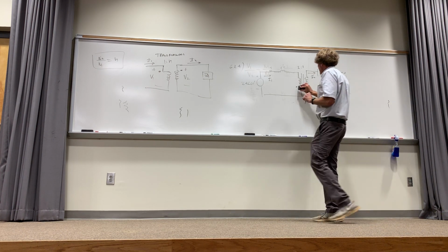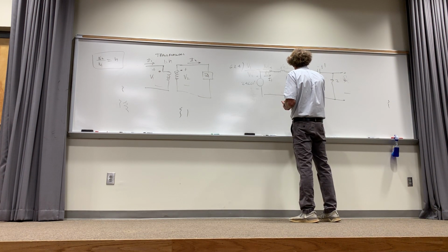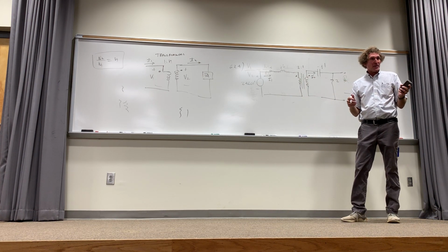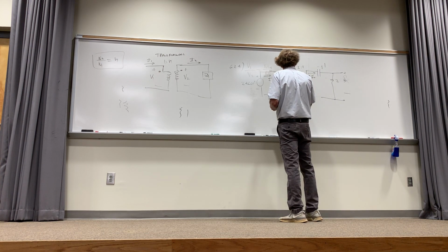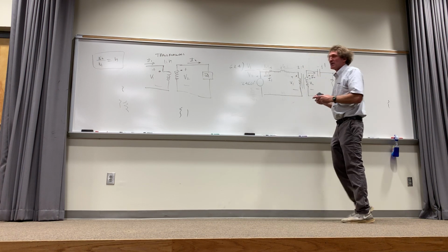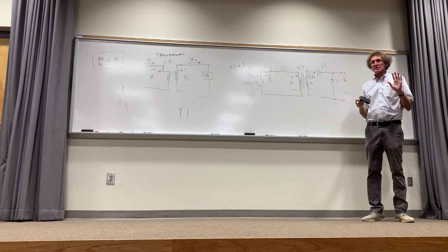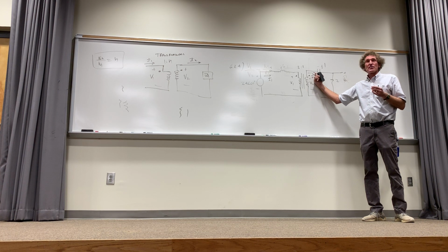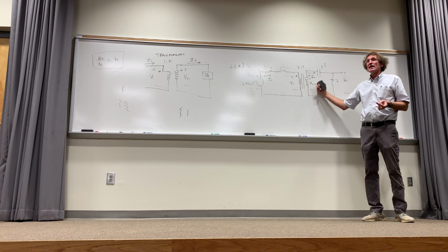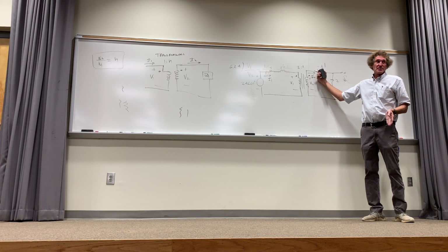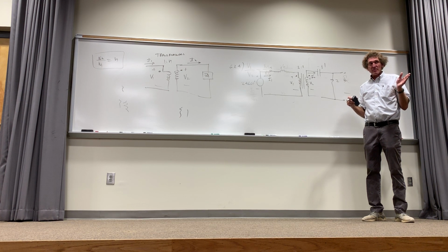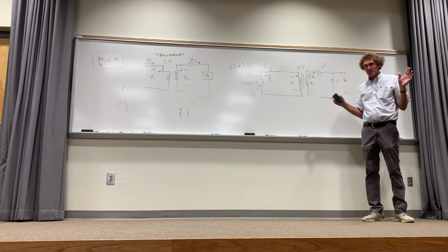You can just go ahead and take those dots and put them here. Now, why did I do that? Because I want my voltage right here. I want to make that V1 and that V2. It will not change a thing. You got that, class? Both dots are on the top or both dots on the bottom. Now, if there's a dot here and a dot down here, when you flip them, they still are going to be on opposite sides. You all see what I'm saying? You get me on this one? Remember, these are AC circuits. That's the reason you can do this.